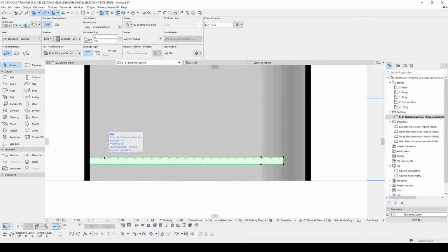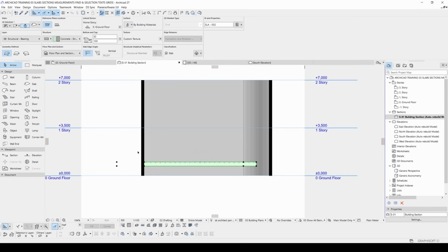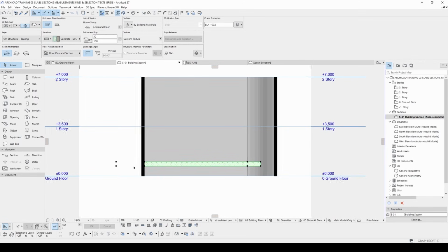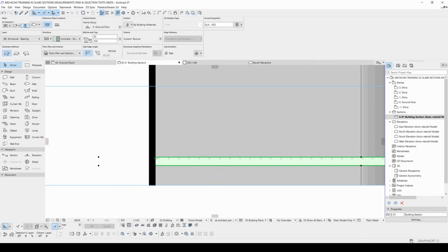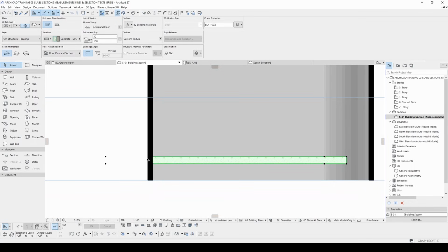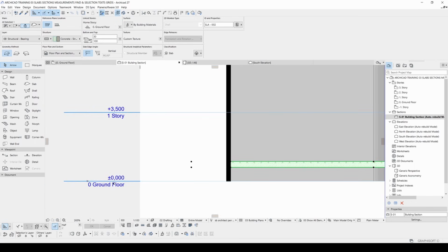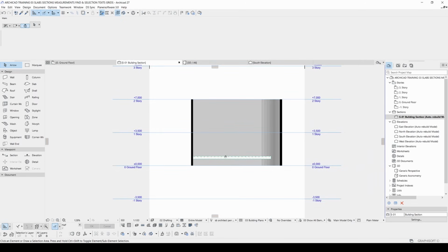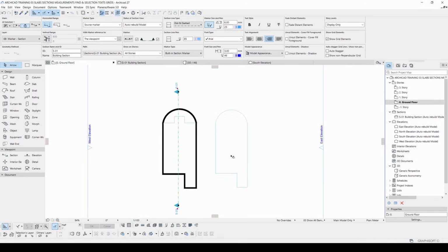You can select and modify your elements such as walls and slabs. You can change the heights. And this top position is 1 meter above this ground floor. If you hit the M, you will see, it will say 1 meter or 100 centimeter. If you hit the F2, you will immediately go back to ground floor and you can continue your documentation progress,